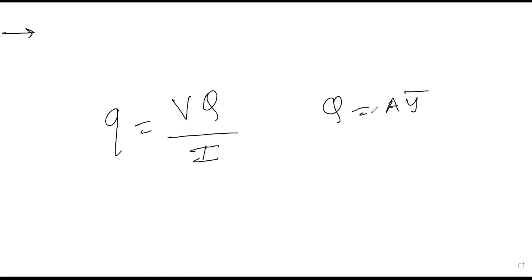As we know, in last lecture we have taken the numericals. In that we have used the equation shear flow is equal to VQ divided by I, where Q is equal to A y bar, and if you have to find out the force due to shear flow, it is nothing but integration of q into dx or ds.